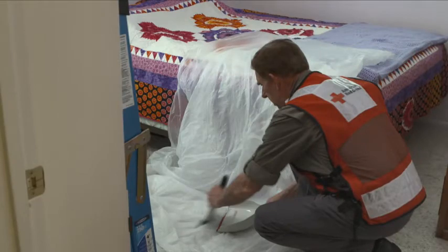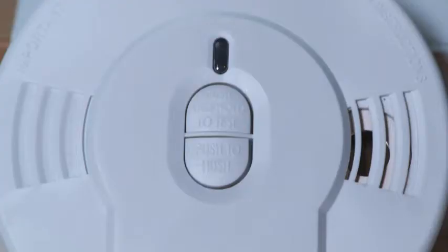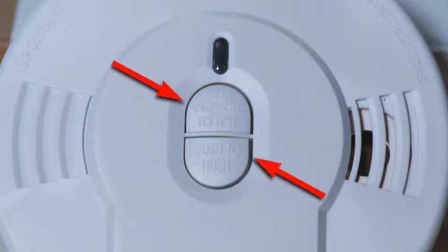The installation of the smoke alarm is now complete. It is a best practice to give the resident the opportunity to perform the test of the alarms with you once all of the installations have been completed. This will familiarize them with the alarm's test and hush features and build confidence that they'll be able to test them once a month and utilize the hush feature. Safety, quality, and effectiveness are the important values that can help save lives with each in-home visit.